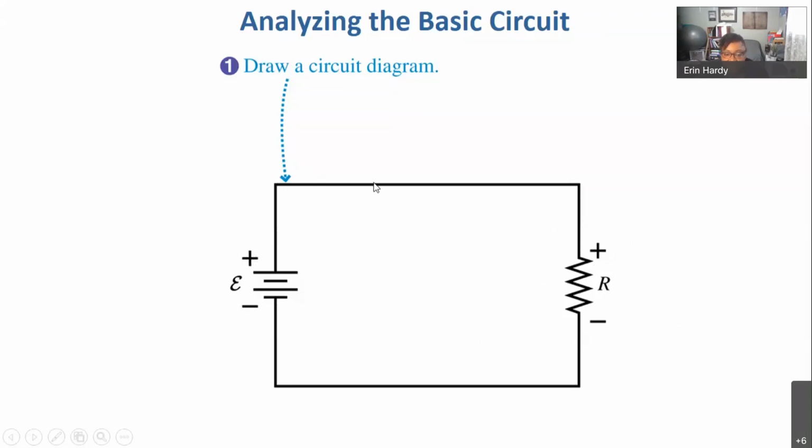If I could trace a charge carrier as it was moving through this ideal wire, the potential value that's coincident with the positive terminal of the battery would be the same as what I would get if I measured on the positive side, or the more positive side, of the resistor. And I emphasize that because resistors don't have charge on their own, but if current is moving through them, then just like the wire segments that we saw in our previous chapter, one end of that resistor will be more positive than the other, and one end will be more negative than the other. So in this case I have just a single resistor, and the part of the resistor that's closer to the positive terminal of the battery is going to be the more positive.